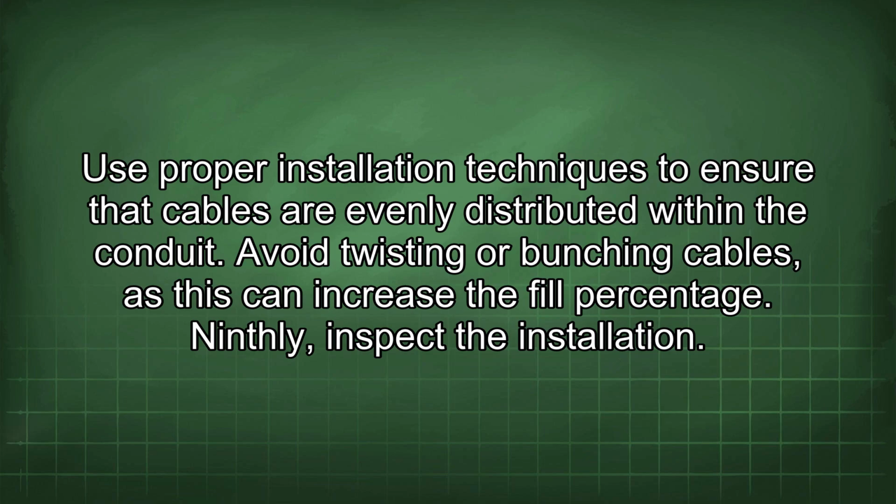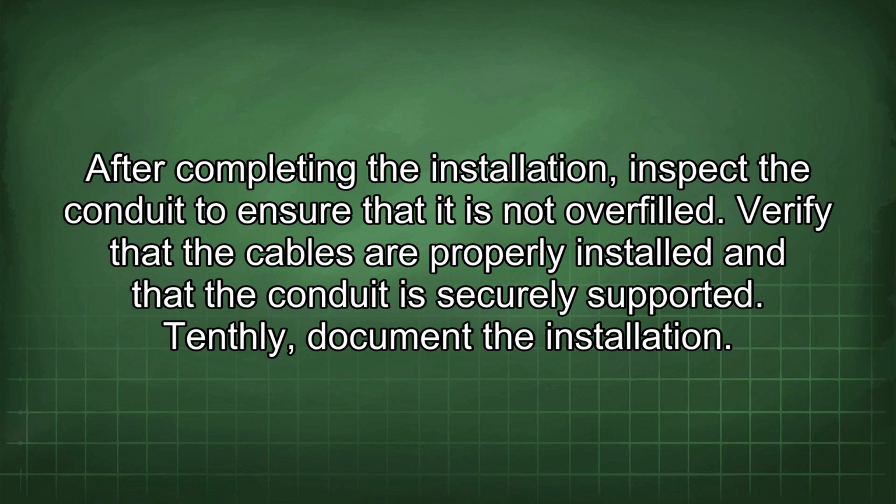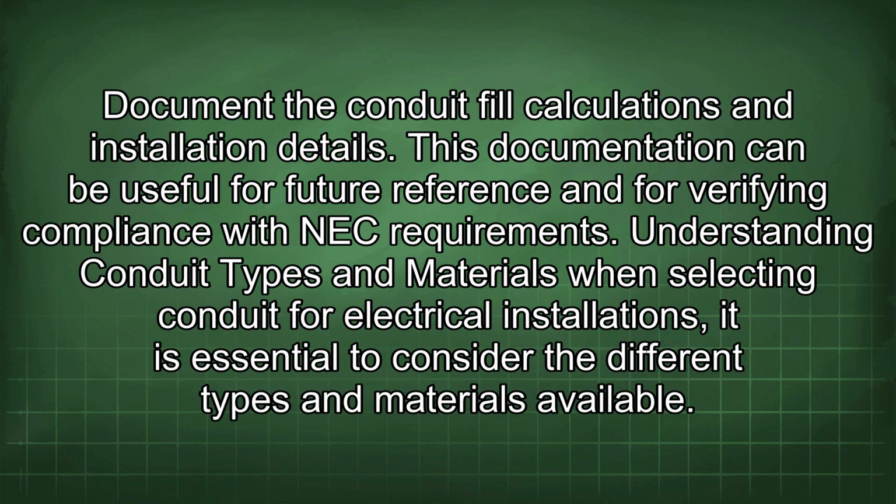Ninthly, inspect the installation. After completing the installation, inspect the conduit to ensure that it is not overfilled. Verify that the cables are properly installed and that the conduit is securely supported. Tenthly, document the installation. Document the conduit fill calculations and installation details. This documentation can be useful for future reference and for verifying compliance with NEC requirements.